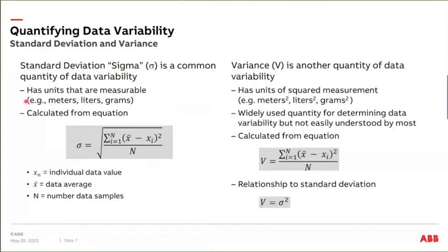If I have a weight measurement in pounds per ream, for example, when I calculate the sigma, that sigma value is also going to be in pounds per ream. This is very common: most of the displays and reports that you would see from a QCS system report everything in sigma, or an X number of sigmas. Very common is 2 sigma.